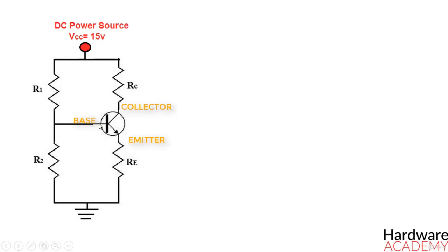If the base emitter is forward biased, meaning that the voltage at this point compared to the ground is greater than usually 0.7 volts, the transistor will open up and let current flow from collector to the emitter all the way down to ground. In this configuration, the base emitter voltage will be around 0.7 volts, so basically you can look at this transistor like it's not even here, it's just a piece of wire connecting RC with RE.